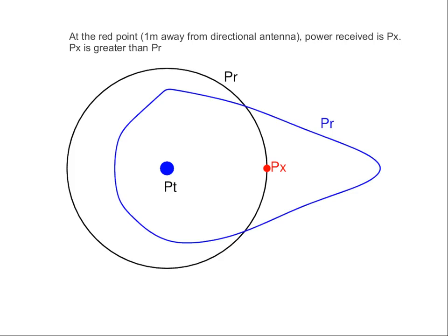A common property that you will see with antennas is what is the highest gain that this antenna can achieve, which is in the direction where we get the highest value. In this example, in this direction. So, with our blue antenna, I can calculate with this example the gain is 2. It's 2 times stronger than an isotropic antenna.